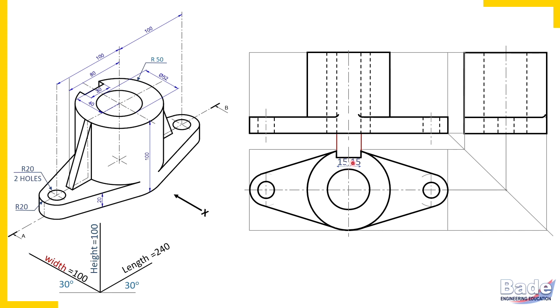Now let's draw this slot in the side view. Check all the details now. Have you realized that the boundary generator of the cylinder, check here, this generator, correct? It is no more here because this portion we have removed. So from the left side, the generator which was initially appearing at the boundary, because of the slot, that boundary generator is no more there. So this boundary we will have to erase.